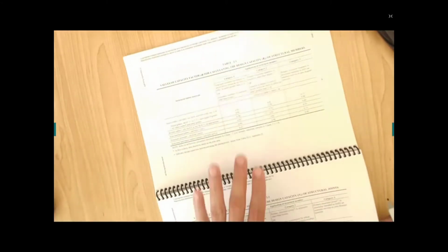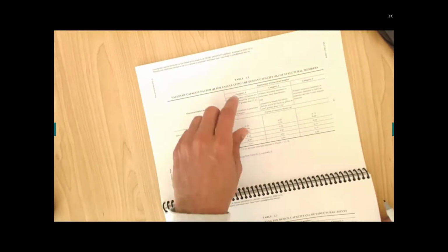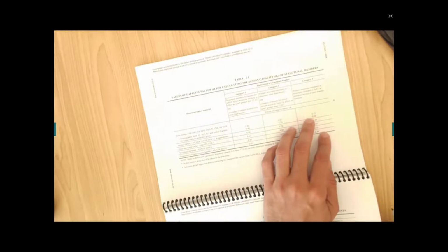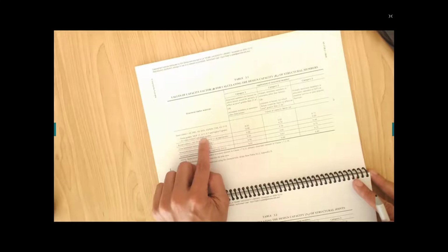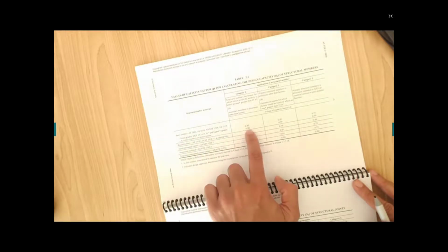Table number 2.1. Don't use Table 2.2. It's for joints. Table 2.1 is for members. We have different categories: category number 1, category number 2, and category number 3. As I mentioned, MGP12 stress grade, MGP10, this one, and higher F grade, all other timber and stress grade. We are not in this category because we have other timbers. We don't have MGP12, we don't have this one. So we are in this line, all others. So we are either this one or these ones. Let me check, so I'm going in the right direction.